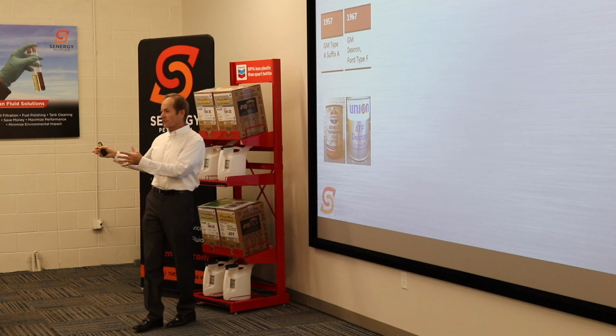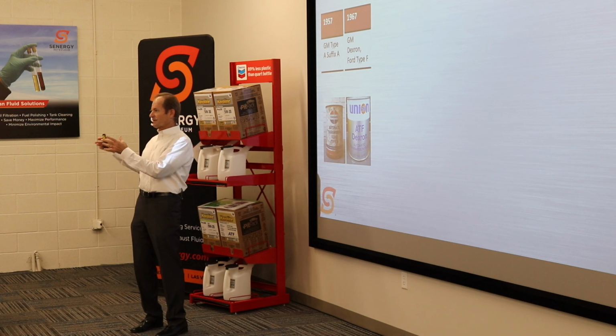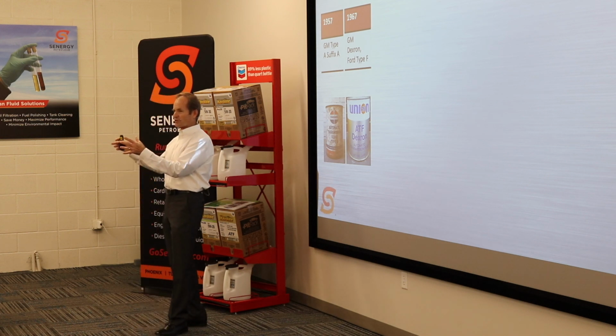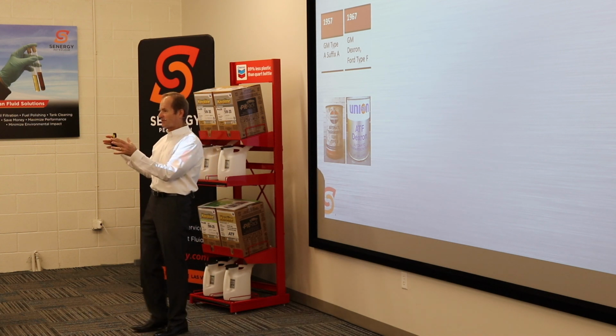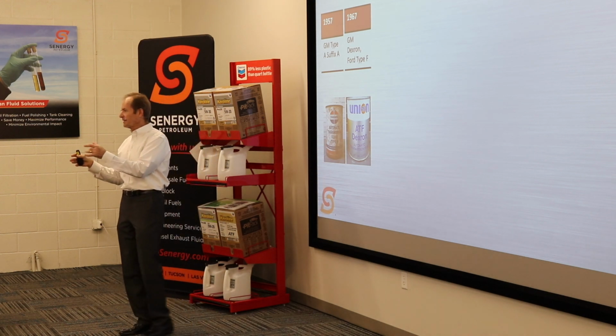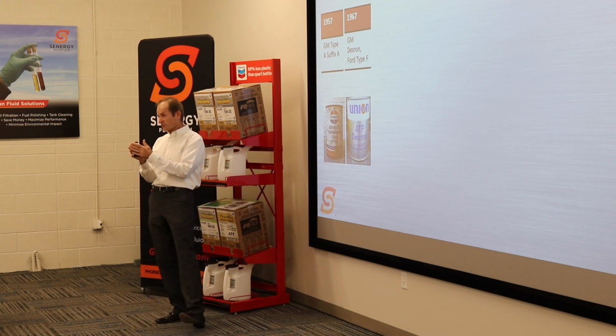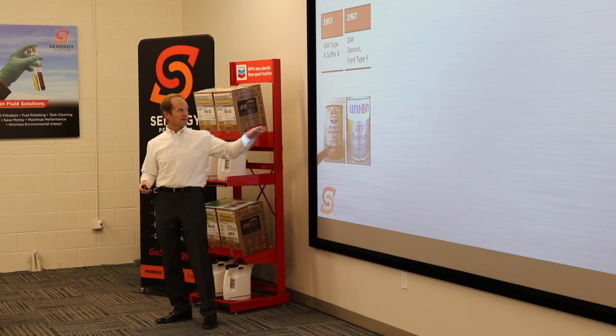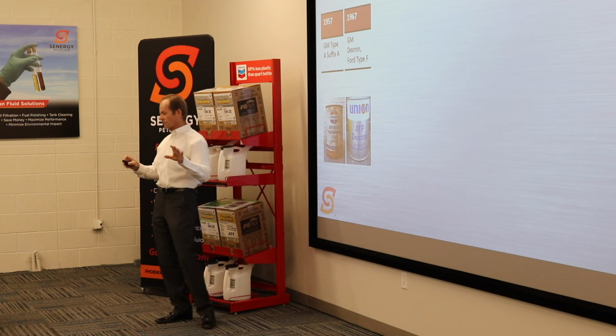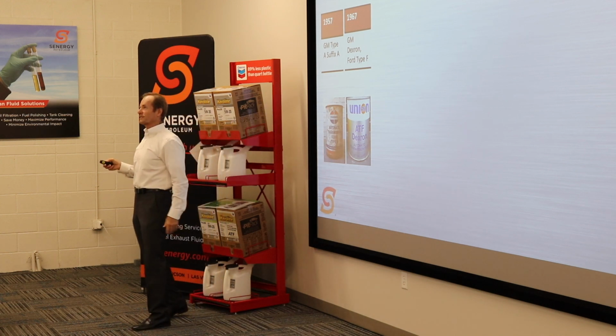The Ford transmission philosophy was different. Ford, for lack of a better term, wanted to make sure you knew that car had shifted. Right? I remember driving my grandfather's '74 LTD, and when we shifted gears, you knew it, all right? So Type F had no such slipperiness additive in it. So Type F and Dexron were mutually exclusive by their frictional characteristics.